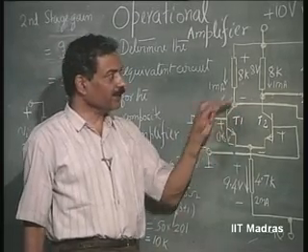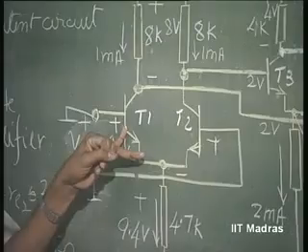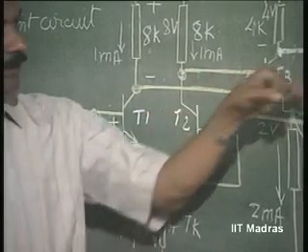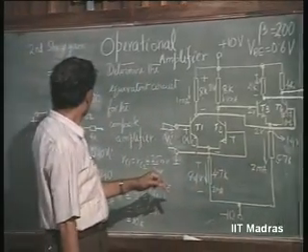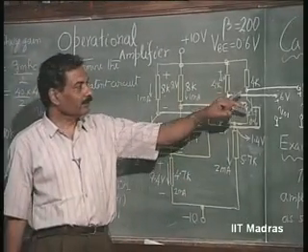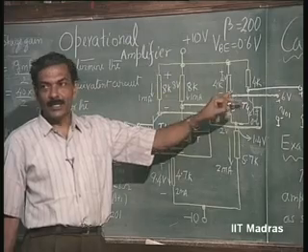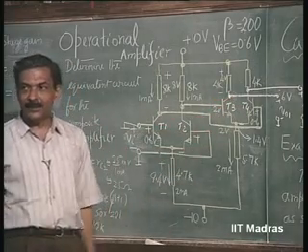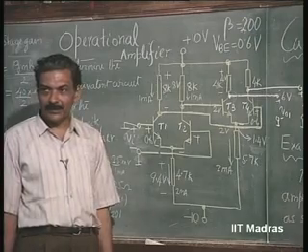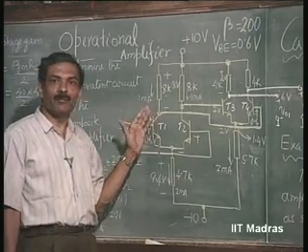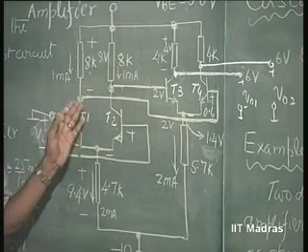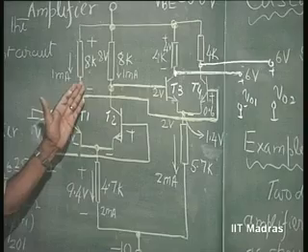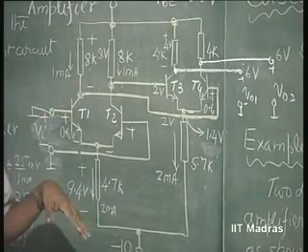That means, this can give you a swing of 2 volts, but that much swing is not needed, because the gain of this entire structure is going to be of the order of 80 or so, right. So, even if you consider 8 volt swing, 8 volts divided by 80 is the voltage swing that is required at this point. You are providing a considerable amount of reverse bias unnecessarily, right. Again, this 2 milliamperes into 8 k is not at all needed here, right.